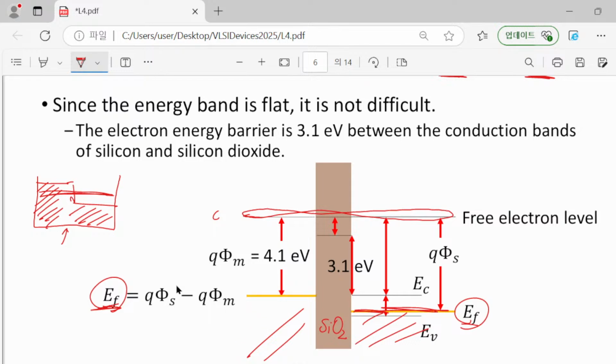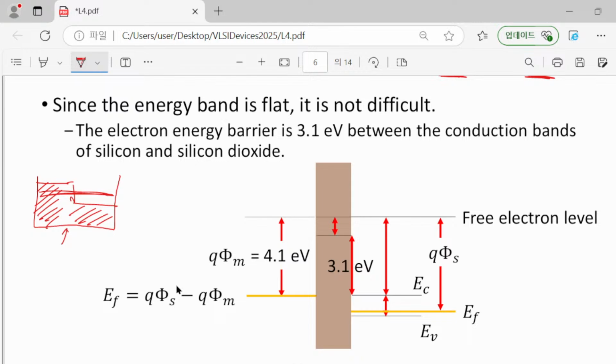Instead the Fermi level is maintained, but here we don't have any gradient of our vacuum level. So this is flat. And if I ask you what is the electric field at this point, then the electric field is just given as the gradient of this vacuum level. So please try to calculate it. That will be just 0. So are you with me?